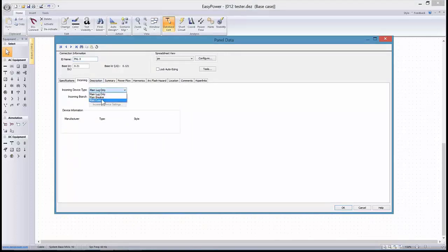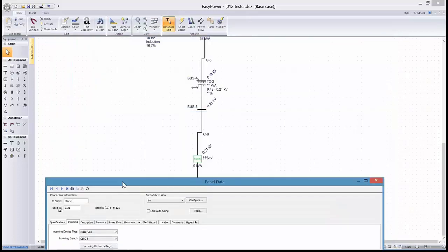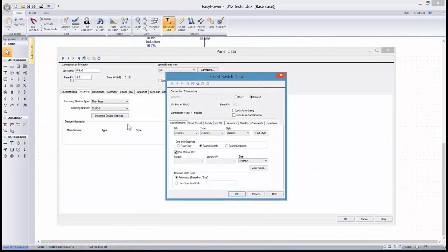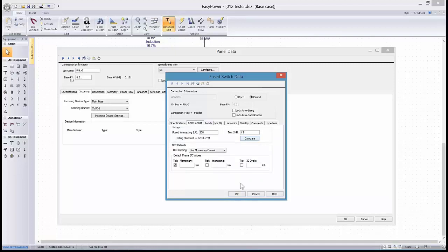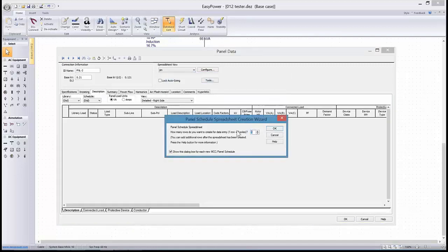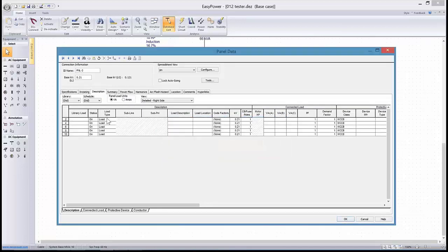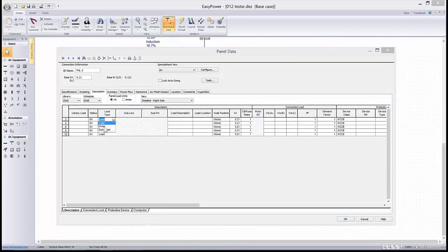Exactly the same deal. I'm going to go ahead and set up with a fuse. It's going to be on C6, which is upstream. We're going to make this a fuse, Aeroflex, and let's go and make it a 100 amp load or a 60 amp load or a 50 amp load. And then let's, besides putting our outboarded panel here, we'll also bring in, so this will be on a single circuit. It is on C7 and it is this panel.